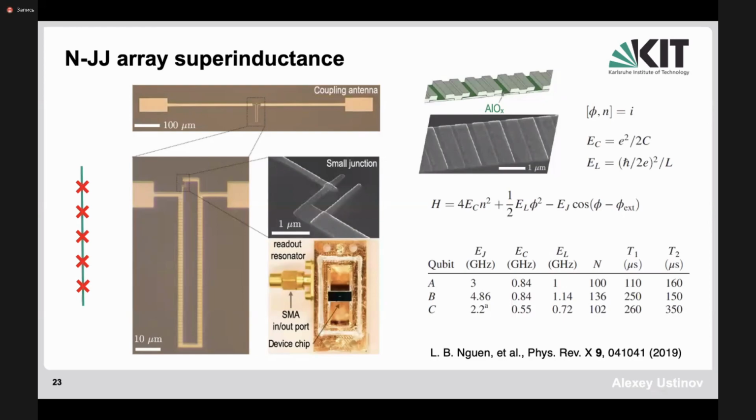For fluxonium, the frequency of transition between 0 and 1, around half flux quantum, is of the order of between half a gigahertz and 1 gigahertz. One doesn't need to do this upconversion, which is needed for transmons. And therefore, experimental life becomes very simple.